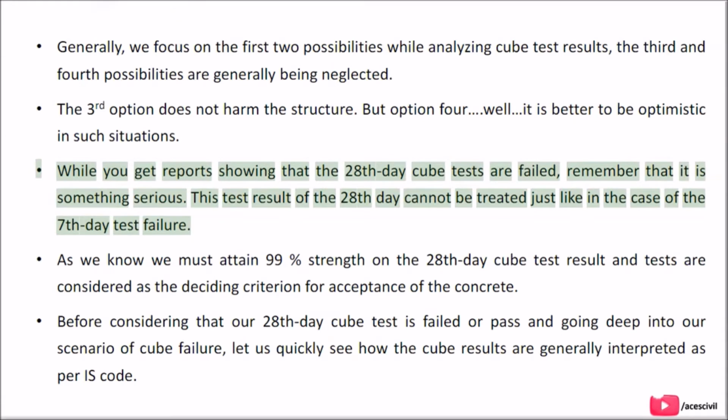While you get reports showing that the 28th day cube tests have failed, remember that it is something serious. This test result of the 28th day cannot be treated just like the case of the 7th day test failure.